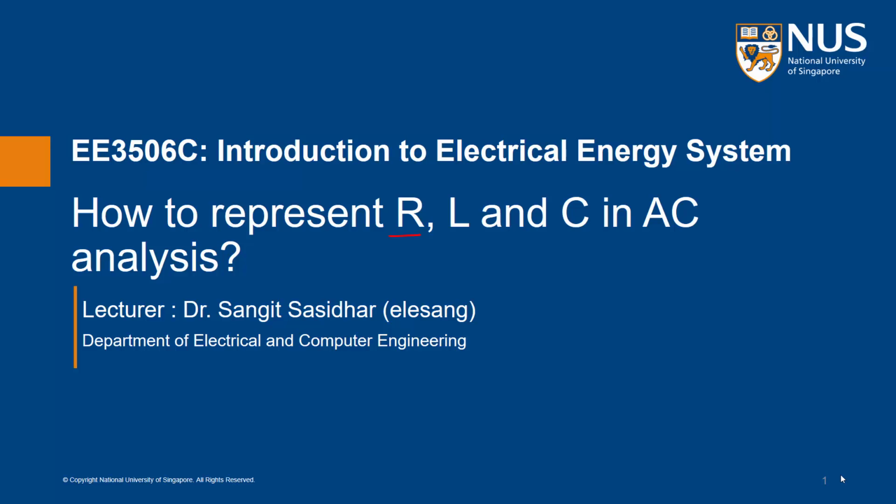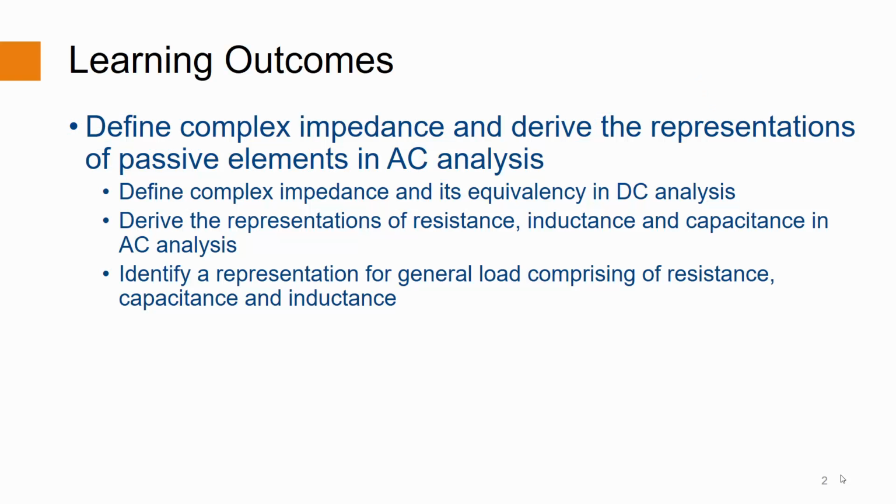Good day class. We will be embarking on understanding fundamentals of AC circuits with this week's series of lecture videos. In this lecture, we will try to derive expressions to represent resistance, inductance and capacitance in AC analysis. We will first define complex impedance and its equivalency in DC analysis, then derive the expression for resistance, inductance and capacitance in an AC circuit, and finally identify a general representation for load comprising of resistance, capacitance and inductance.